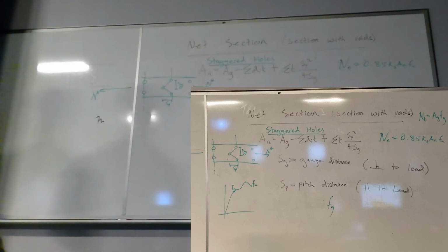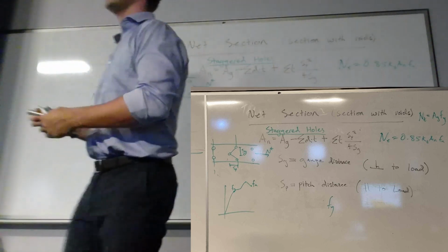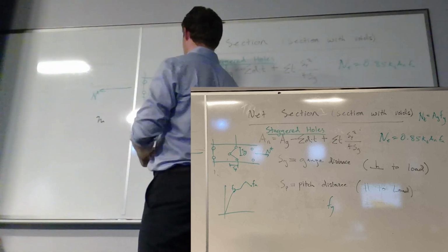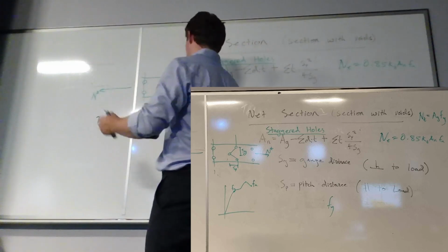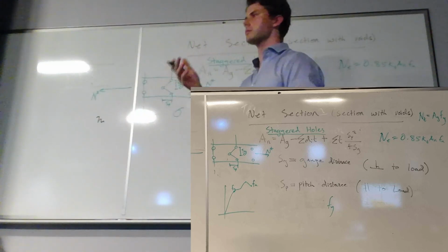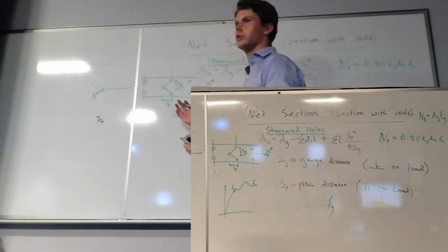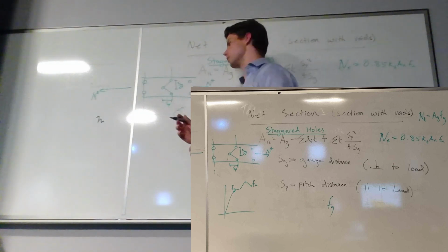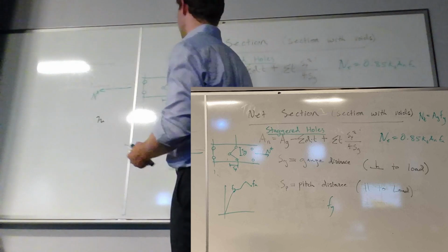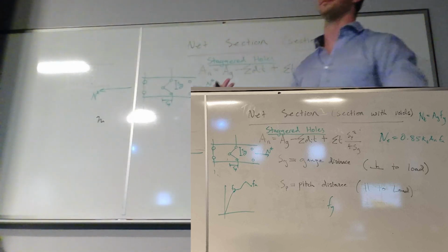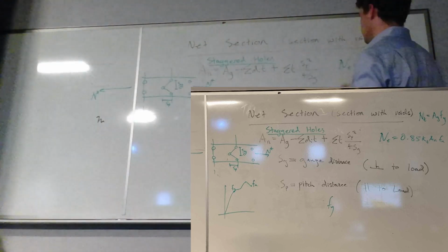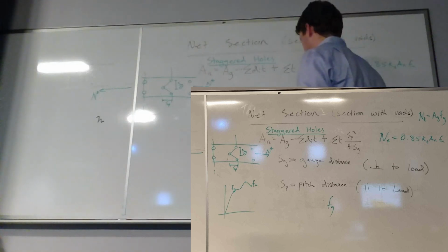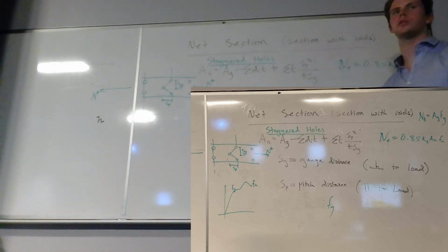Yeah, F, or you might be thinking sigma, like this one. Yeah, sure. That's your stress, right? So like yield stress when you do Young's modulus and all that. But when we write it in steel design, we write yield stress as Fy. So when you see Fy, that's yield stress. When you see Fu, that's ultimate strength. Which one's higher?